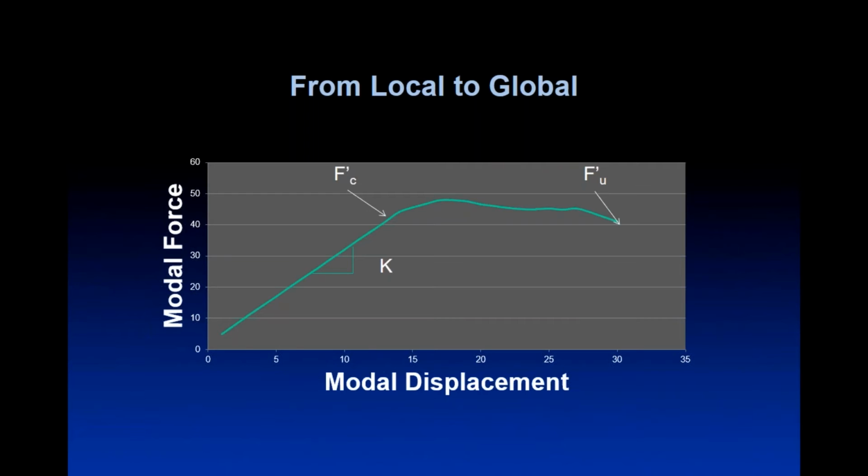Now here, for a long time, we've had a problem, and that's why there's been this discussion between wind and earthquake engineers. First of all, measuring frequency, that's really quite simple. Expectation of frequency is really quite simple. It's fairly well defined by the geometry of a structure. It's not very much changed by the material. There are small differences between concrete and steel, but they're probably about 10%.